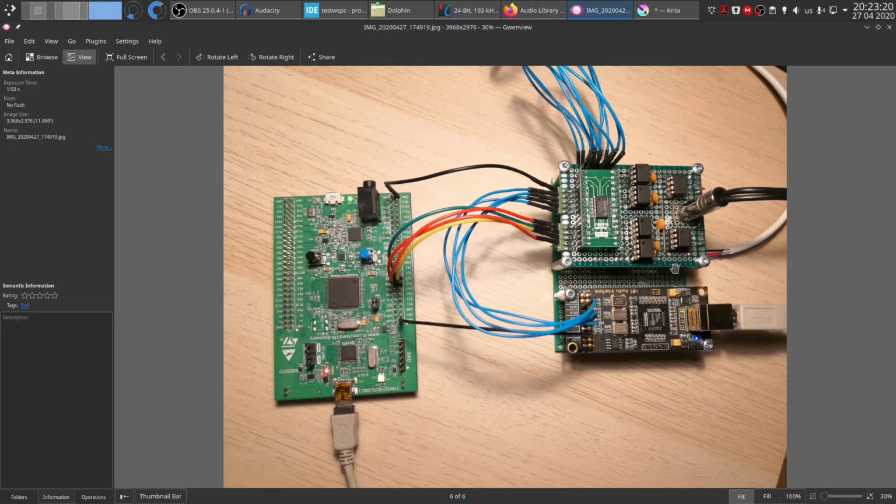And over here is the actual DAC board. This daughter board is the one that has all the analog circuitry on the output, and it has the actual DAC on its breakout board over here, so it can be easily accessed on the standard 0.1 inch header, or in this case 0.1 inch raster of a board. And under that is a motherboard, you could call it that. I have a few standoffs because under here there's a power supply. The daughter board and the motherboard are connected with these wires, so these are all the supply pins.